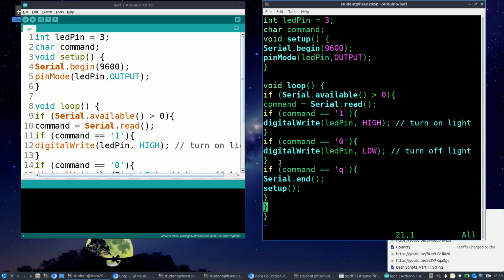270, so it's red, purple, brown, and then a gold. So there should be 4 stripes on the resistor, okay? Did you actually have words on yours? Because the one I have is just a little piece of tape with no words. But yeah, if you have a piece of tape that has 270R, that's the correct one, okay? But verify when you look at the stripes to make sure it's the right one, okay? Anybody need any assistance?